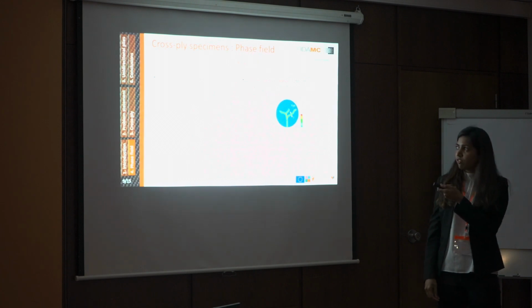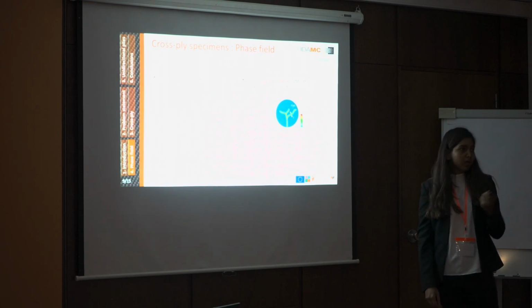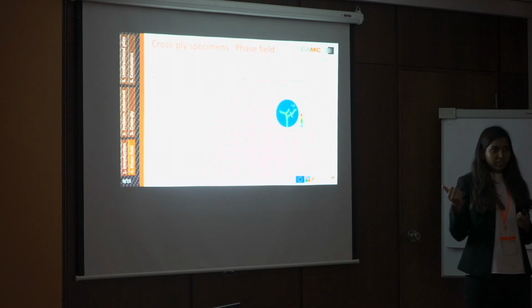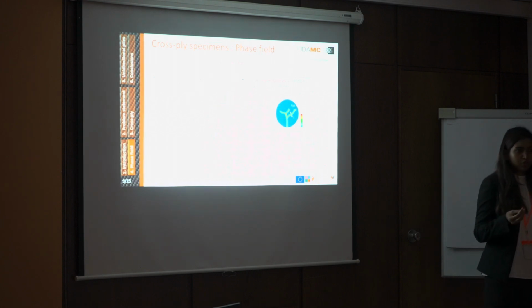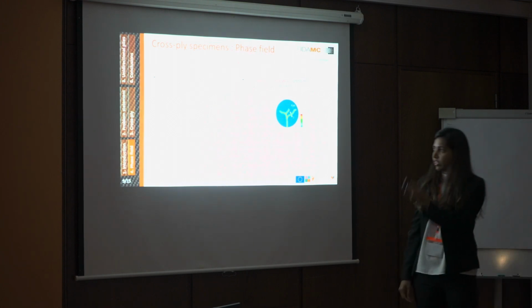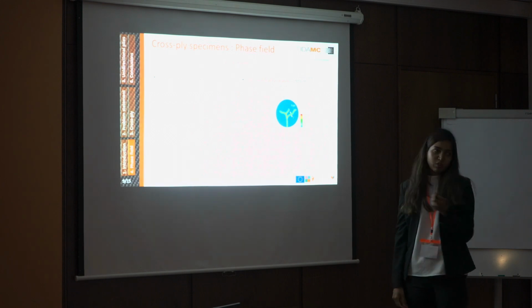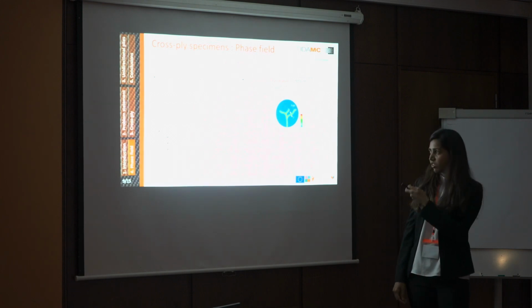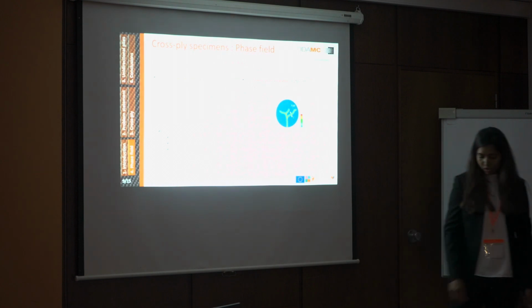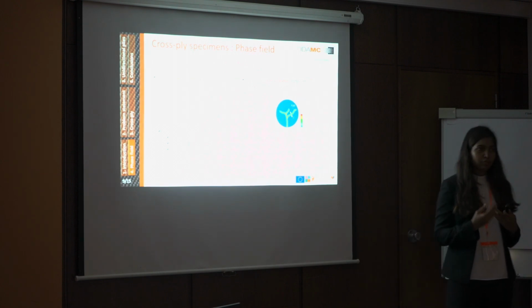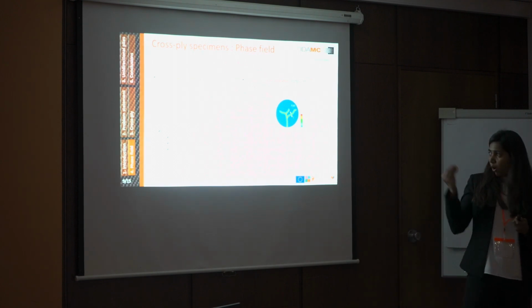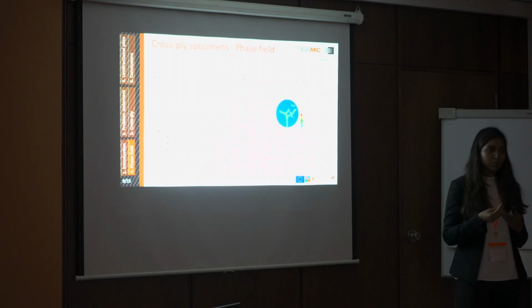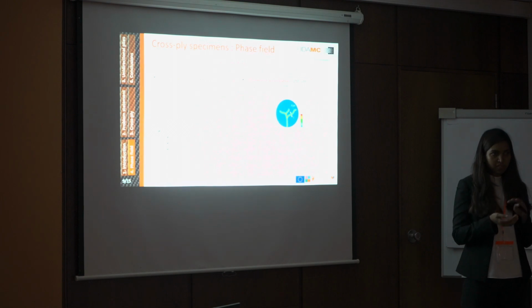I'm not getting into details of phase field because my colleague Zeng already presented phase field, and there were a lot of presentations yesterday on phase field. So this is the phase field variable which varies from 0 to 1. 0 is no damage, 1 is complete damage. And we tested 3 formulations, AT1, AT2 and phase field cohesive zone formulation. All this is implemented in a simple Abaqus subroutine by Professor Emilio Martinez-Pineda. So we are using his code as a basis of our work, and we are developing further according to our problem needs.